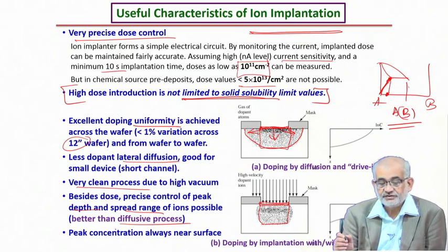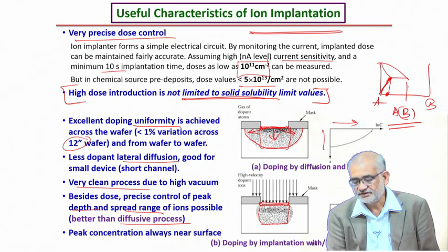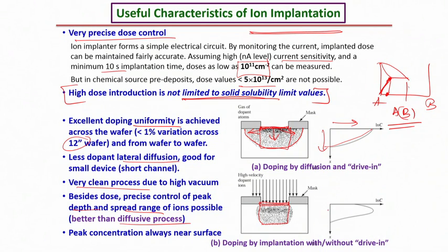And also what we know is that in a typical diffusion control process, if this is the concentration and this is the depth, the concentration will be highest at the surface and then decrease as you go below the surface. In case of ion implantation, the peak concentration is not at the surface but slightly below the surface. But even then, this peak is not way below the surface.